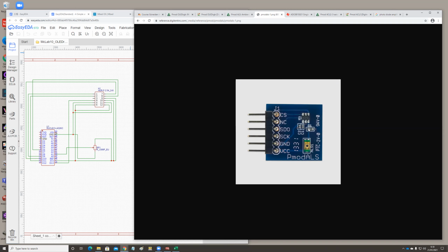And then we measure the voltage over this resistor with an analog to digital converter. That's the simple circuit in here. What we get out of the analog to digital converter is a digital number, a binary number, which goes through the sensor data out to the microcontroller.